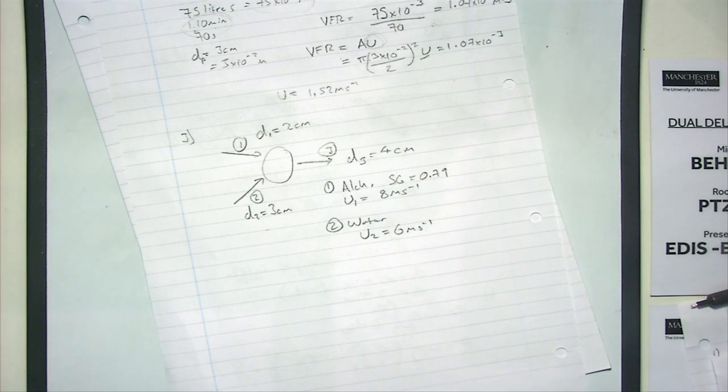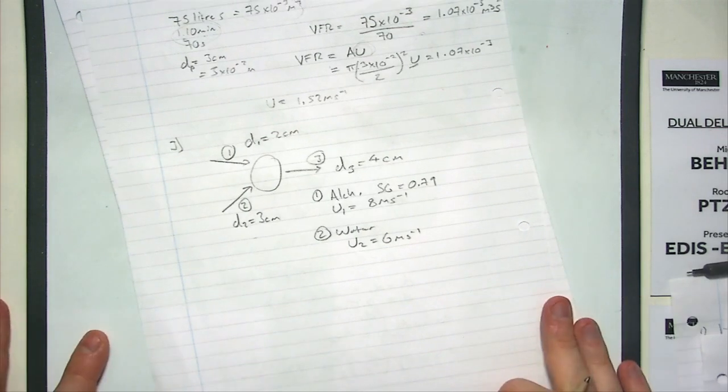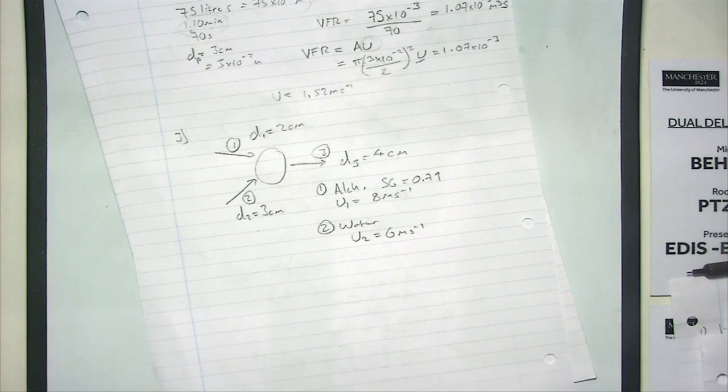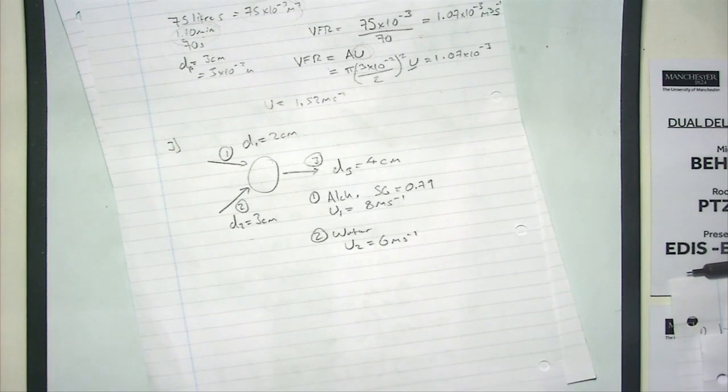Okay, so coming out of the pipe at part 3. So fluids that we deal with in fluids 1 are incompressible, right? So we can write that their volumetric flow rates are the same because of the continuity equation, right? What comes in must go out. What comes in must equal what comes out, okay?